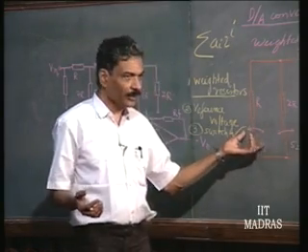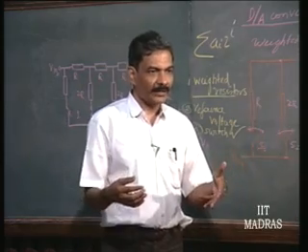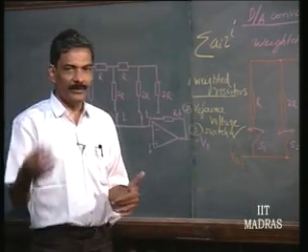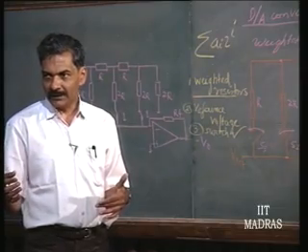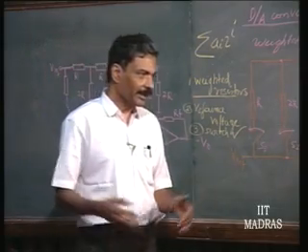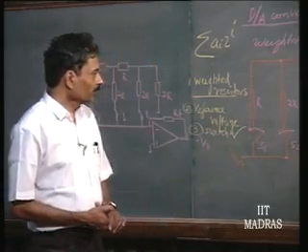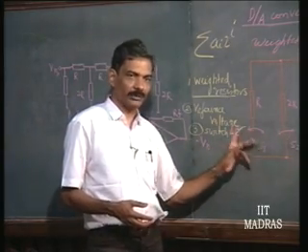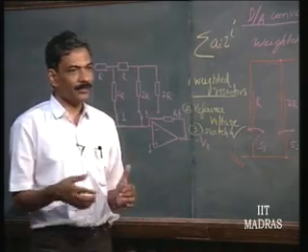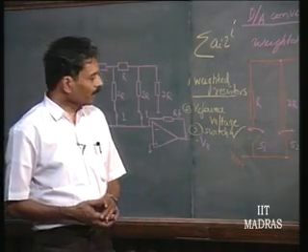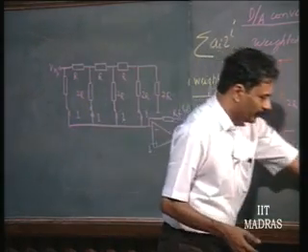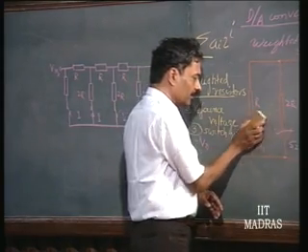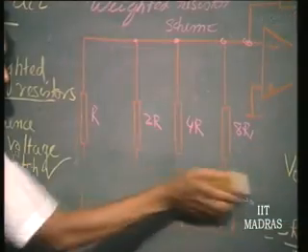The voltage across the switch is 0 or V reference. That means, the capacitor across the switch has to be charged up to V reference, right. So, before you take the output, therefore, there is going to be some limitation due to the nature of the switch itself. So, how do you get over this problem? This problem of the switch can be got over neatly by doing what is called current switching. What is that? Simply put the switch,